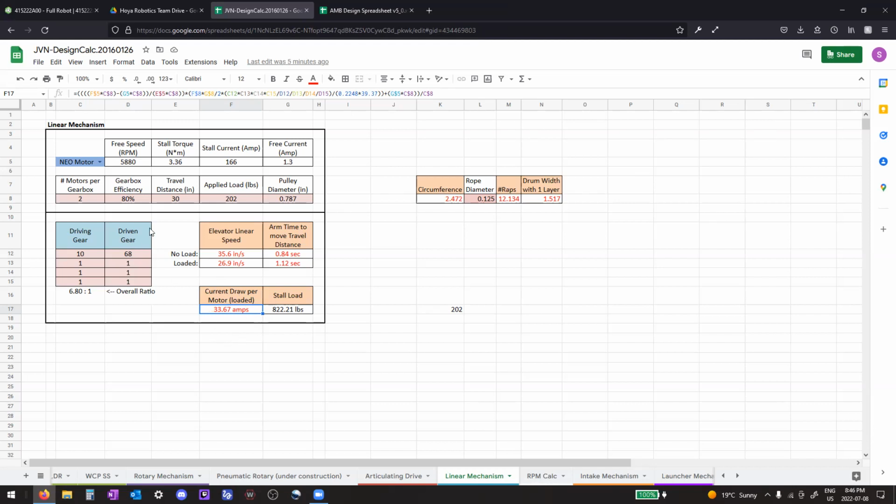But that's how we calculate. That's how our climbs were, when our climbs were working, that's why they were really fast, because we used this to calculate it and to really push the limits of it as fast as we could. We didn't just put a really big gearbox on it. We put the smallest possible gearbox on it, while being within some sort of safety margin.